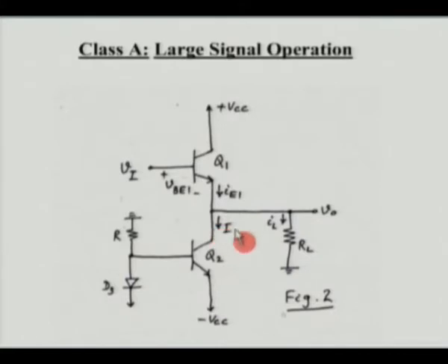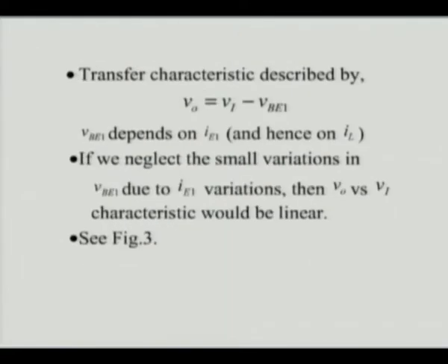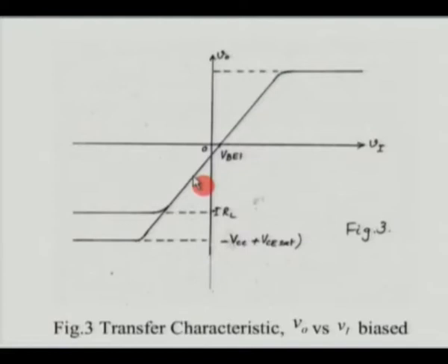But again, depending on the current which you have chosen here, you can have another limit. In case you are constrained by the current you have chosen there, then the negative limit will be minus of I RL. We must remember that we have chosen I in such a way that the positive peak of it is greater than the negative peak.